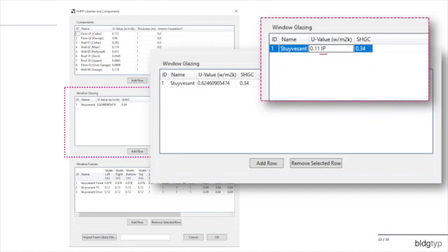The way that I've built the tool is that by default, everything's in metric. The EnergyPlus simulation's all in metric. Honeybee's all in metric. So those other tools that we're working with are all in metric. So by default, it works in metric. But sometimes I like to enter things in IP. So I've created the tool in a way where if that's what you want to enter, just say it. If you want to enter an IP U value, just say 0.11 IP, and the tool is smart enough to know what you meant, and it'll do all the conversion for you. I think that's true across the board, pretty much anywhere where you're asked to input data. If you just say, oh, this is inches, or oh, this is IP, it's smart enough to do all of that conversion for you.